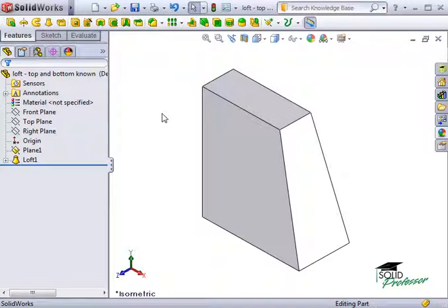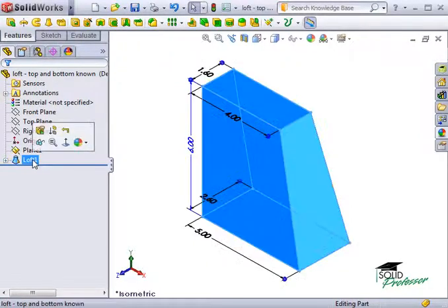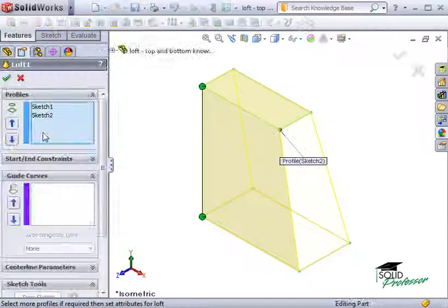If you would like to change the appearance of the side faces, one option you have is to apply constraints to either the beginning of the loft, the end of the loft, or both. Let's take a look at how this is done. I'll begin by editing the loft feature and expanding the section labeled Start and Constraints.